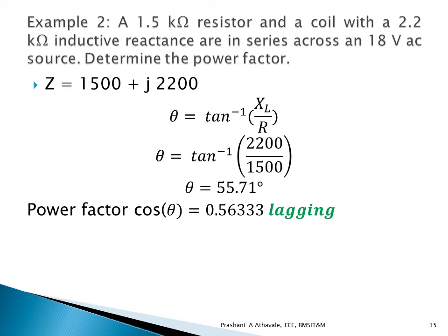Here it's said that a 1.5 kilo ohm resistor is connected in series with a 2.2 kilo ohm inductive reactance. There is no mention of inductance and we don't require it over here also. We just require the value of XL and value of R, both of them in ohms only. And this is being connected across an 18 volt source.